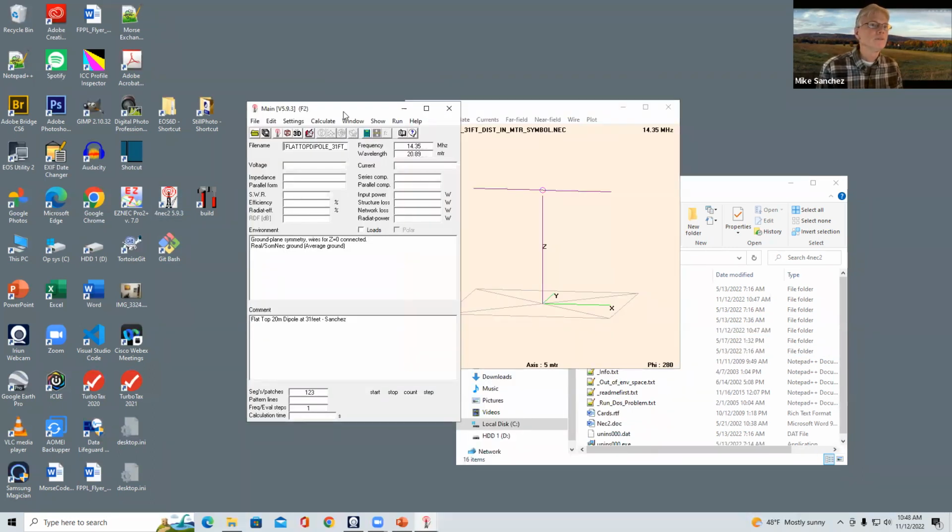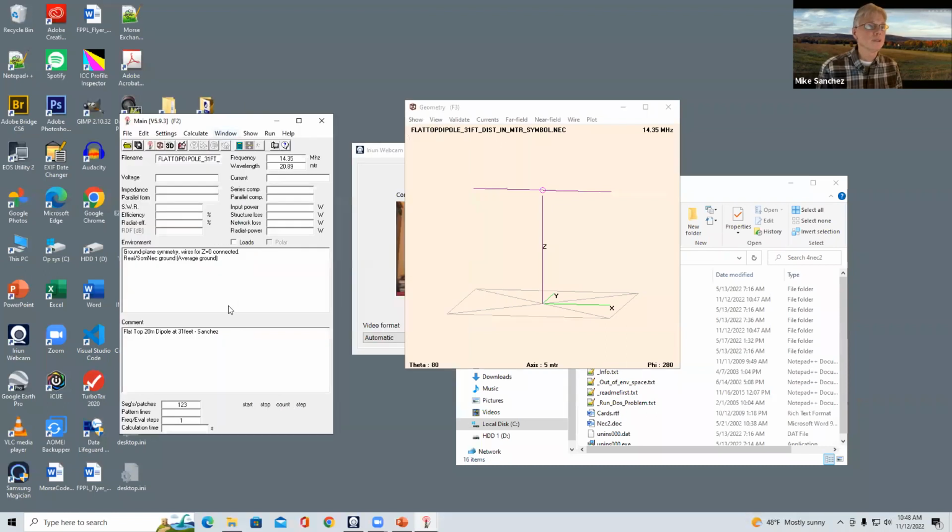And we have the correct frequency. So, gentlemen, this is what I fed back to Ari like 8 years ago, and it's never been fixed. If you're paying attention while you're doing various things and changing things, you have to be careful to make sure that what you thought you typed into the model actually is being picked up, because sometimes it's not. So now I'm going to rerun this model to give it the initial condition.